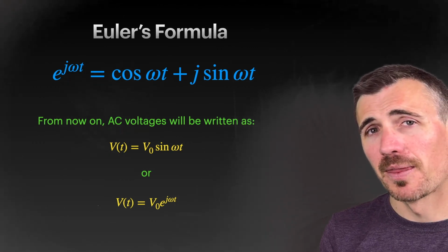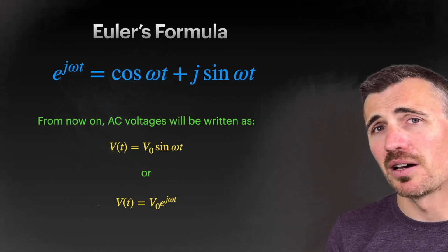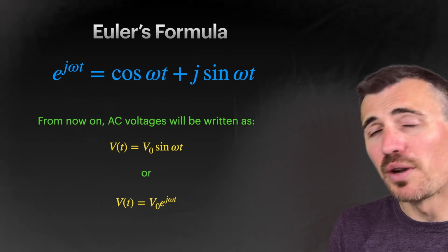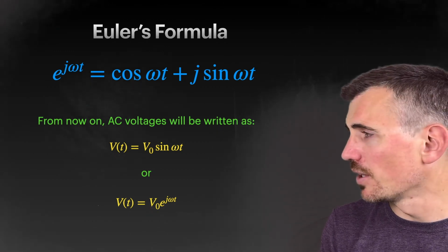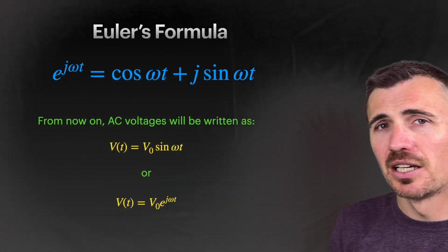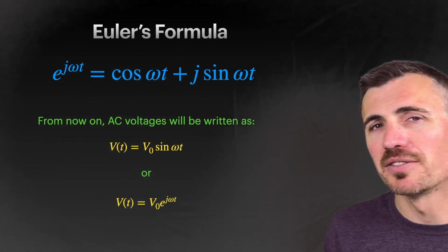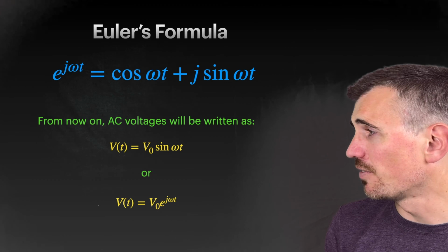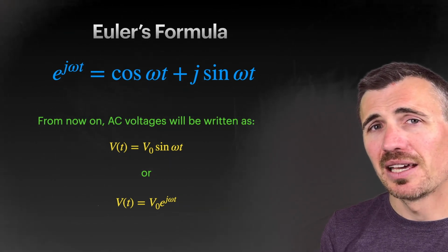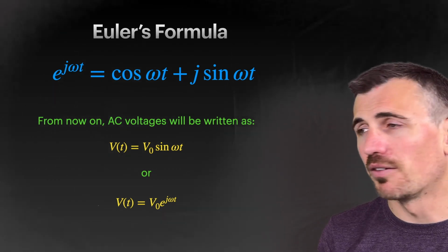The next important thing, I think, is that there's a magnitude and a phase associated with sine waves, and we can either think about them as things that happen in time, or frequencies which are happening at a given time. All right, so we can talk about a time domain description of a voltage going up and down like this, or a frequency domain description which represents what happens to all the sines and cosine waves. Finally, just a reminder what a phase is, we're going to come across it a lot. It's merely a shift forwards or backwards in time. And keep that in mind when we're talking about the phase shift, the lead or the lag of high pass and low pass filters.